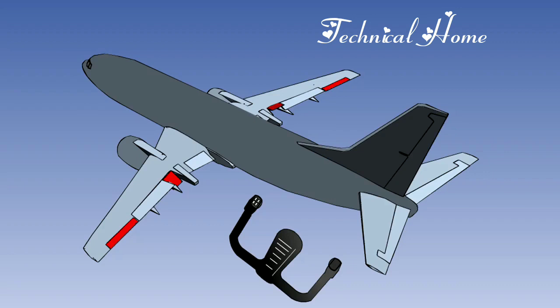But once the flaps are retracted, the outboard ailerons are locked out, and only the inboards operate. On others, the outboard ailerons are used in isolation until the flaps are retracted. The system then switches to the inboards only.